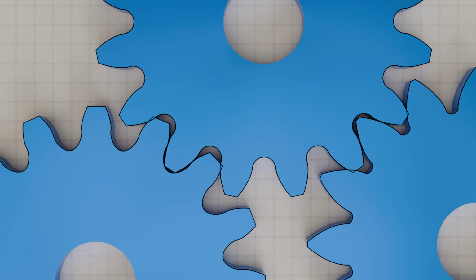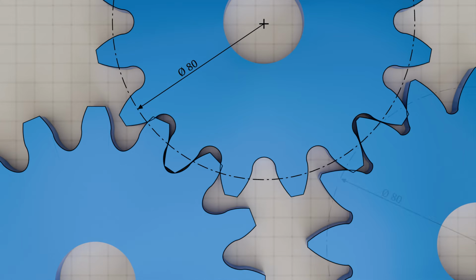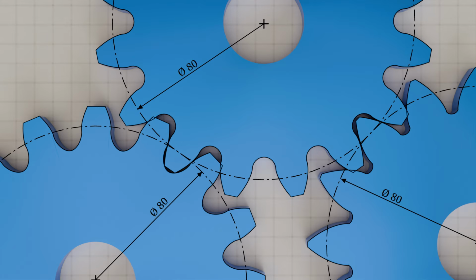The image shows gears that all have the same module of 5, the same number of teeth of 16, and therefore also the same reference pitch circle diameter of 80 mm. The other parameters we have learnt so far, such as circular pitch, tooth thickness, and tooth space width on the reference pitch circle, are also the same for all three gears. Moreover, all teeth have an involute shape. Nevertheless, there are clear differences in the tooth shape, which lead to an interference of the teeth in mesh.